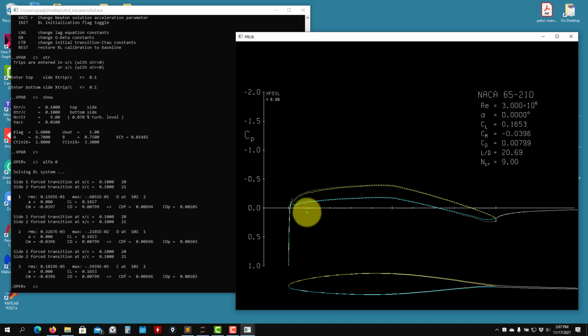So see that now we're forcing the flow, and you see the influence here to become turbulent. These have a lot of implications we saw during the lectures. Now, the most important one is that you are bursting that laminar separation bubble, which in some cases can be very dangerous. At high Reynolds number, 3 million, they are not very dangerous, but sometimes you can operate at lower Reynolds, about 500,000, 300,000, 100,000, and there those laminar separation bubbles can be really dangerous because